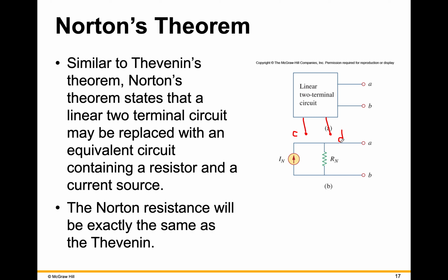So you've got to be very careful that you maintain these terminals. You don't want them to get absorbed in a source transformation or anything unusual that you would do to simplify the circuit. Otherwise, you've eliminated the terminals at which you're trying to find the Thevenin equivalent. That's a problem I observe pretty often as far as common errors that people make on exams.